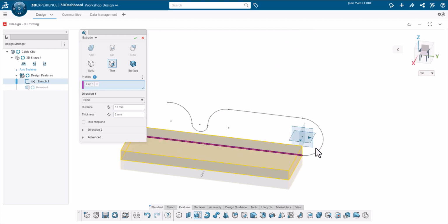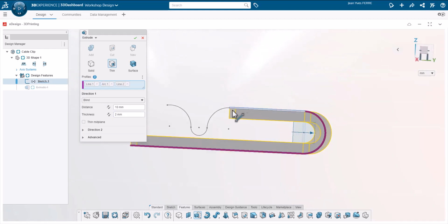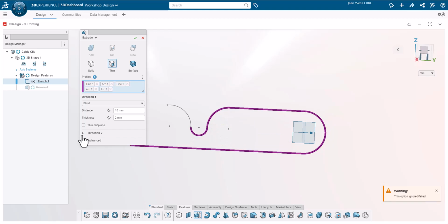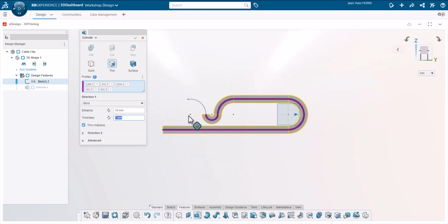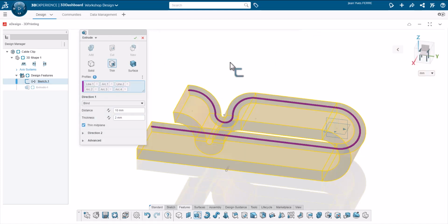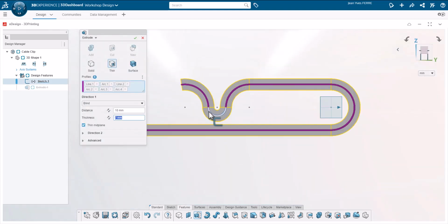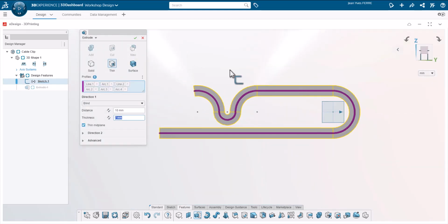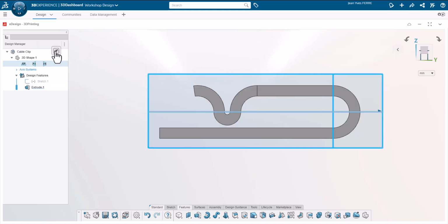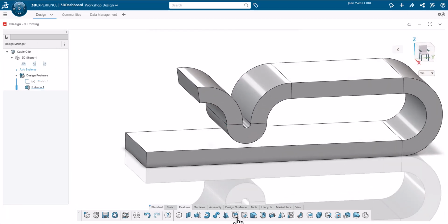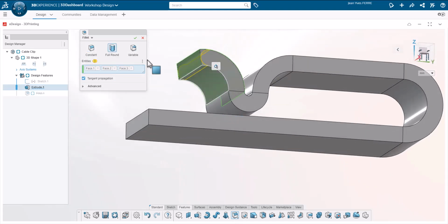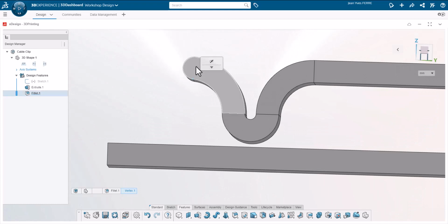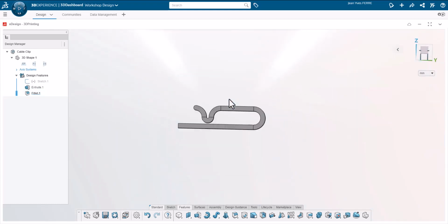In the meantime, I will create some material from this sketch, and to do that I will choose thin extrusion, which gives a thickness to an open sketch. I select entities one by one and see that system stops when geometry would intersect itself with this 2 mm thickness. I just choose thin midplane to balance material on each side of the sketch, and now it works. Changing dimensions would have also solved this issue, of course, but this is too complex for me right now.